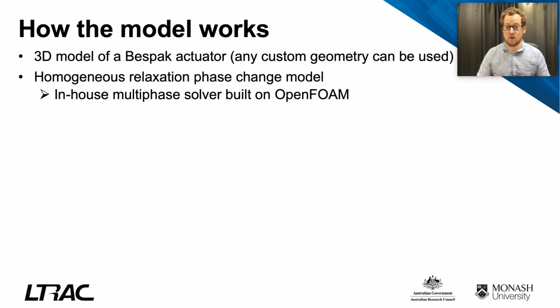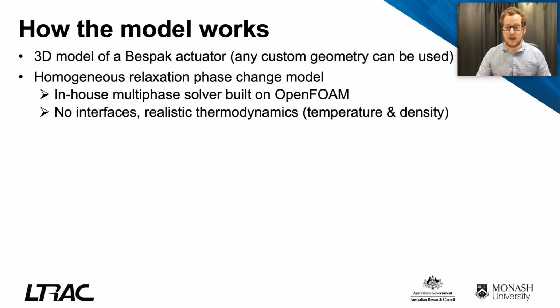So it's built on OpenFOAM, which is an open source computational fluid dynamics package, but it's an in-house solver that we've developed ourselves. It doesn't model the individual droplets or gas-liquid interfaces to save computational cost. We use local averaging within each grid cell, but we do include realistic thermodynamics. So we include the temperature and density relations and pressure relations for any formulation, and we can customize the thermodynamic property data for whatever formulation we like.